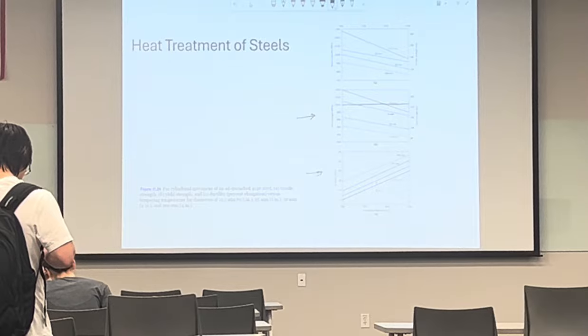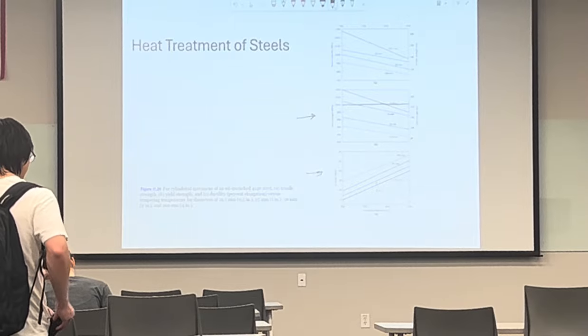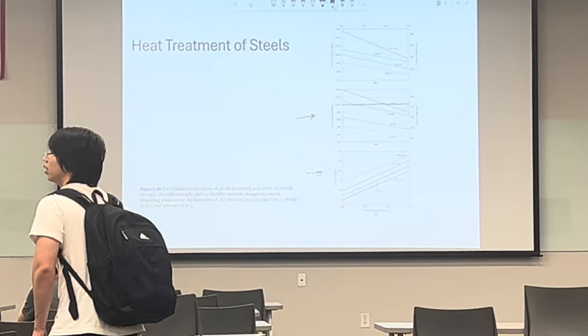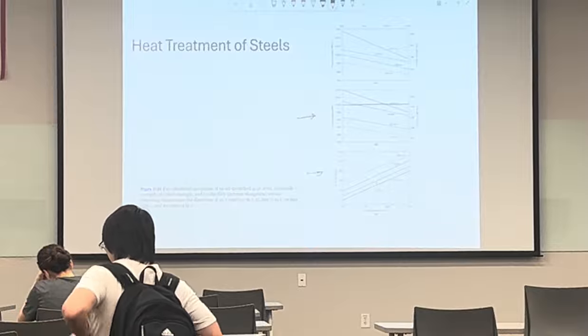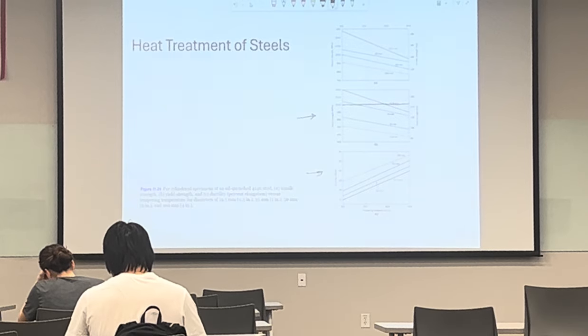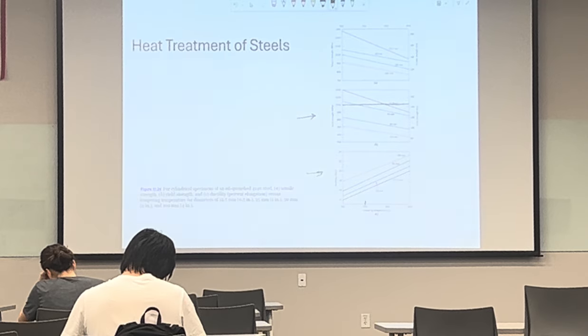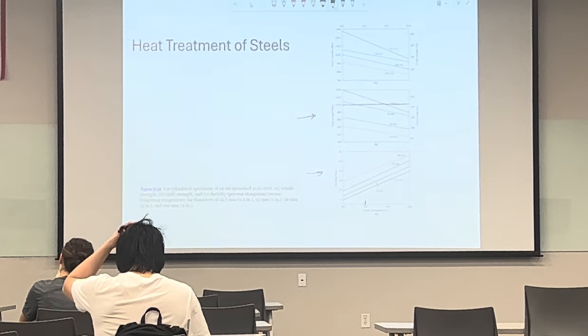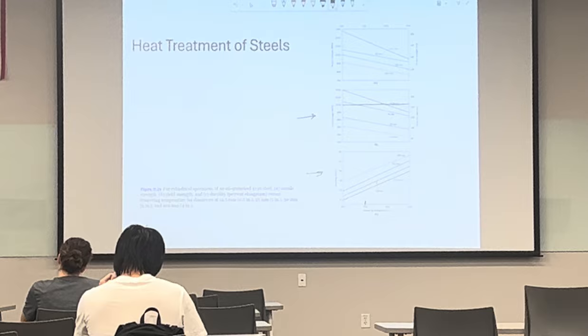And so, knowing this, from the next figure down, 11.24C, for the 12.5 mm diameter line, the tempering temperature is greater than about 550 degrees Celsius, which is, so 550 is here. It's going to give a ductility greater than 16% elongation.